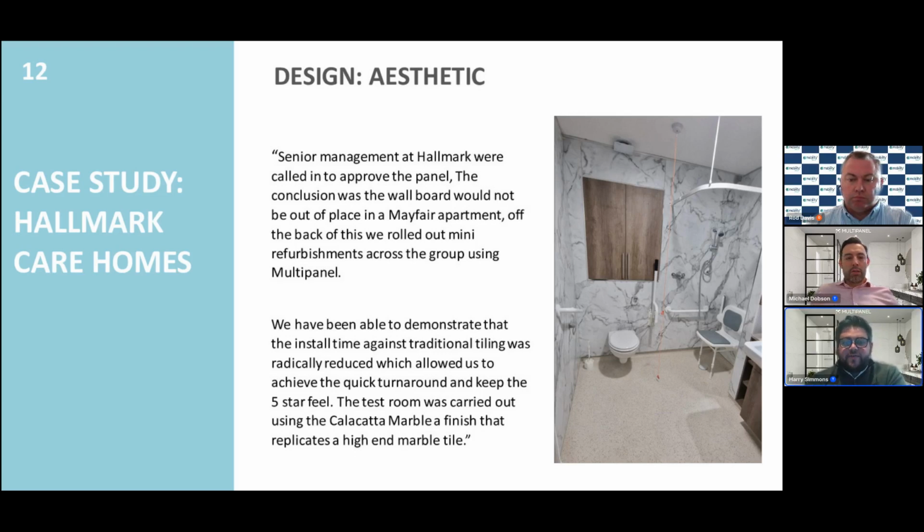There's another question that's actually quite relevant to this bathroom. Do we have different panel sizes for smaller areas? This bathroom here used our standard 1200 wide panels, but Hallmark have also been using some varied sizes. Our standard width is 1200 wide. We also do 900 wide and then 598 wide. Hallmark have used some of the smaller panels for smaller toilets and also areas of the building where it was difficult to carry up the 1200 wide panels. So they went for the smaller options, so it's easy to handle. It's a one person lift with a 600 panel weighing 9 to 12 kilos.